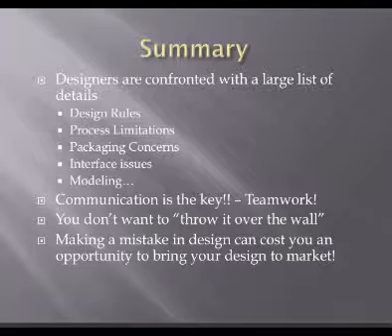Okay, and of course, teamwork is really important, because one person can't do it all. Right? So you might be designing a small part of a whole MEMS device. So you got to talk to the other designers. The design team has to talk to the fabrication team. Hey, will this work? Can I make a 0.2 micron space? No. How can we make a 0.2 micron space? Oh, well, we can deposit really thin films. So if you want to make a 0.2 micron space, we can play games with deposition. We don't have to do lithography. Then you start going down that path.